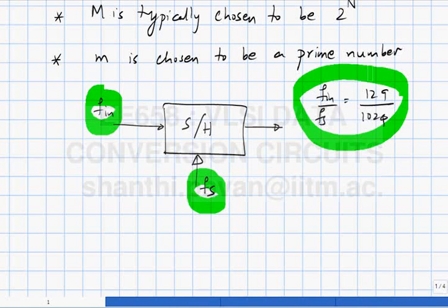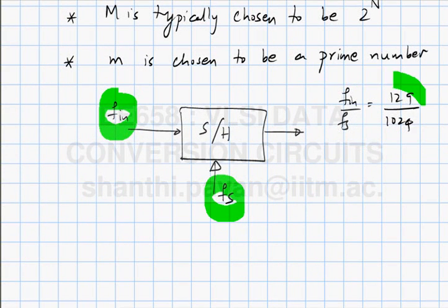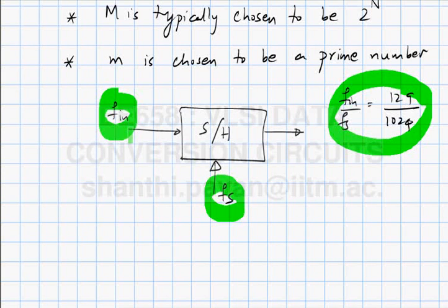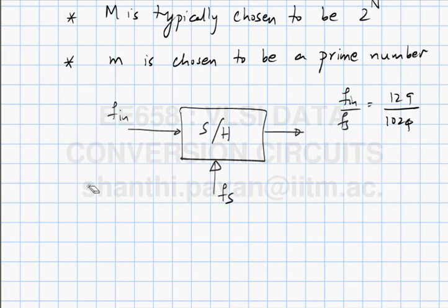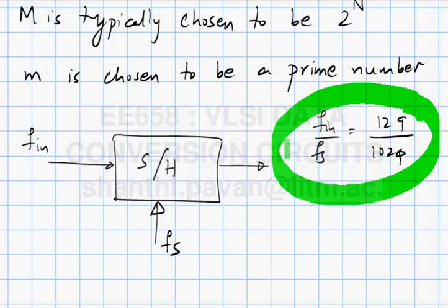So you can use a phase lock loop to make these two clock sources be in sync, such that they follow this. The basic idea is to make one dependent on the other. If you buy high-end signal generators today, you will find that you can connect one box up to the other box, and the two of them will talk to each other and figure out whatever they need to do to make sure that their frequencies are set in this precise manner, or whatever manner you choose, for all time.